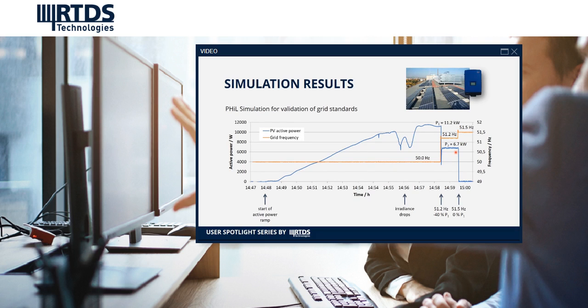Afterwards, I increased the grid frequency to 51.5 Hertz, which is the frequency which I already mentioned. At this frequency, the converter shall be disconnected according to the standard. And indeed, the power drops down to 0 watt.